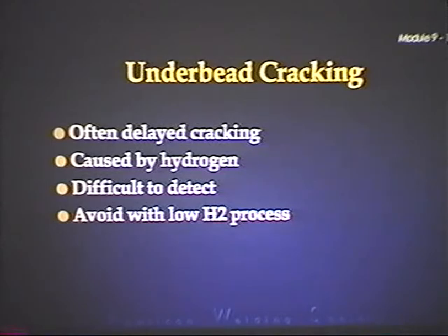So, again, reading from your book, it says, if the weld metal cools more slowly, some of the hydrogen gas that has been dissolved will have an opportunity to escape from the weld by precipitating out. That's what I was talking about. If you post-weld heat treat it, or you can throw a blanket over it, or you can take a rosebud and warm it up, let it cool off slowly, then it can have a chance to precipitate out. But if it cools quickly, then it's going to get trapped in there and it's going to exert that pressure.